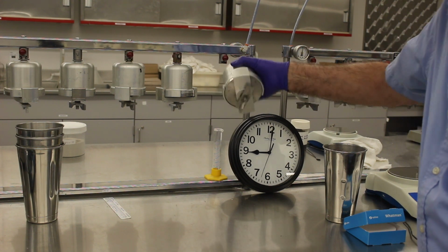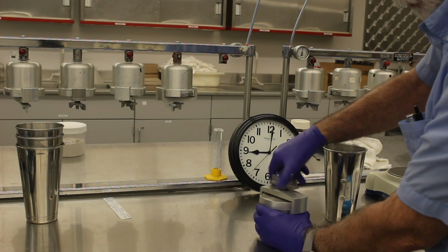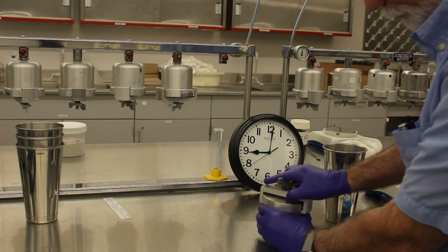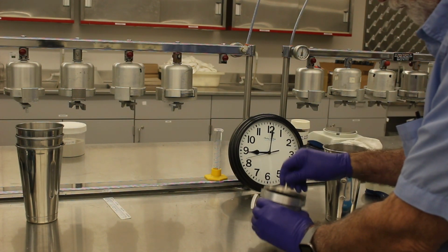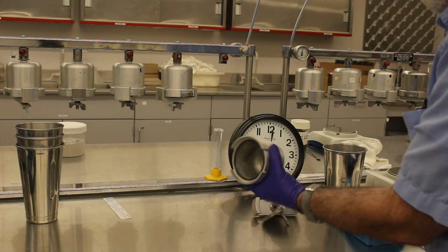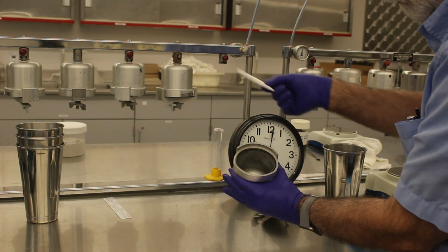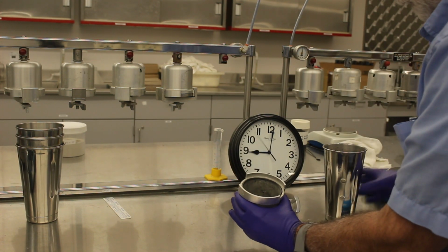The drilling fluid chamber is made of materials resistant to strongly alkaline solutions and is so fitted that a pressure medium can be conveniently admitted into and bled from the top. The design is also such that a sheet of 9-centimeter filter paper can be placed in the bottom of the chamber just above a suitable support.